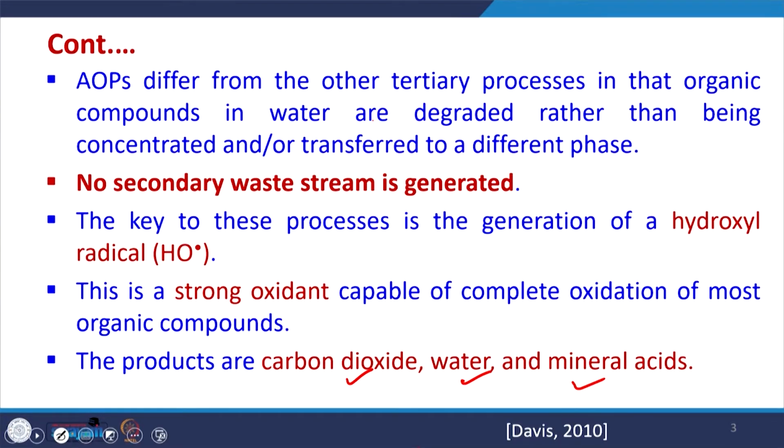So, what does it mean? Here we are converting any organic compound, CxHyOz or anything with S, N etc., into CO2, H2O etc. So, we are totally mineralizing them, whereas in some other techniques that we have studied in the tertiary processes, like adsorption, the pollutant moves from water into the solid phase.